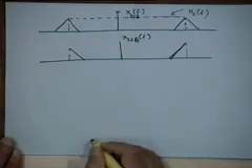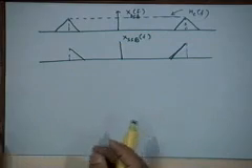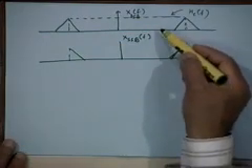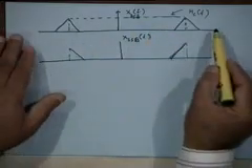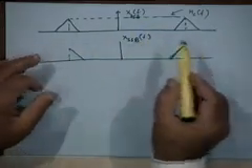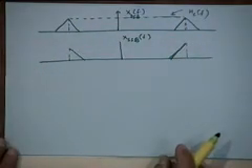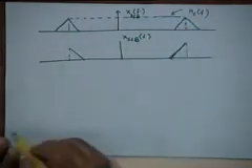Right, after this low pass filtering. So this is the process through which the SSB waveform is generated in the frequency domain, right. Multiplication of the DSB-SC spectrum with the transfer function of this kind of an ideal low pass filter, right. So now let's look at this ideal low pass filter.